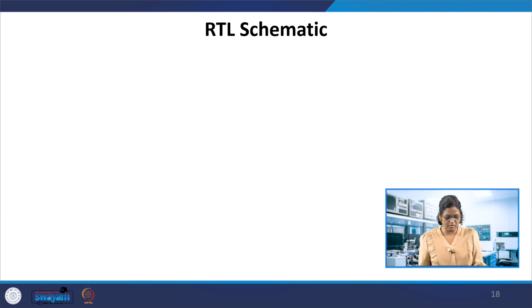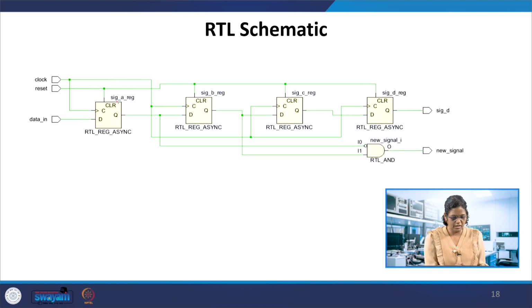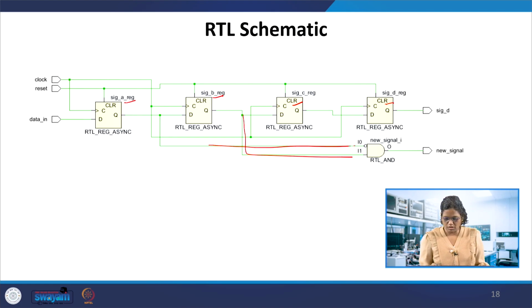Now the realization of this: signal A, at the passage of the clock, takes B, C and D, and B is taken and A is inverted, and a new signal is formed because we have the assign statement separately and we did not even initialize that inside the if reset is 1. So it is not under the influence of the passage of the clock, and this new signal is only combinational logic. Over here you can see the absence of the flip-flop. This signal is unregistered now.